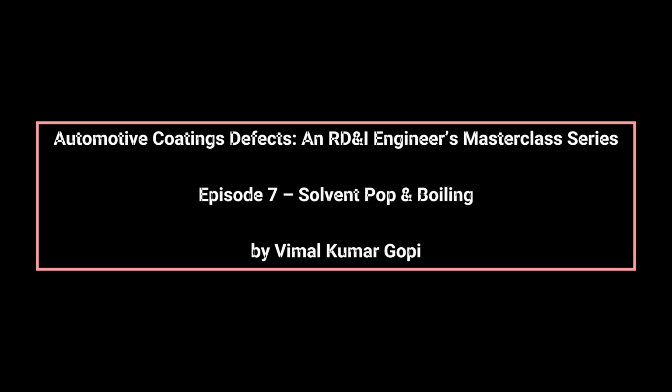Attempts to polish or bury solvent pop under additional layers only mask the defect temporarily and often lead to durability failures later. From an OEM troubleshooting standpoint, solvent pop must be approached systematically. First, verify actual film builds across the panel, not just target values. Second, audit real flash-off times under production conditions, not laboratory assumptions.